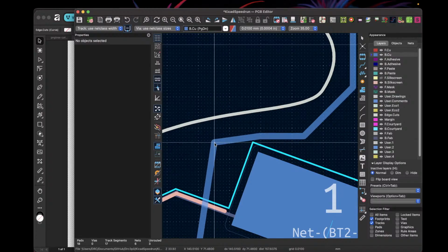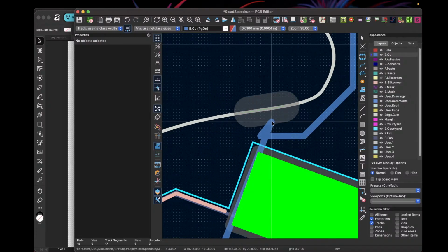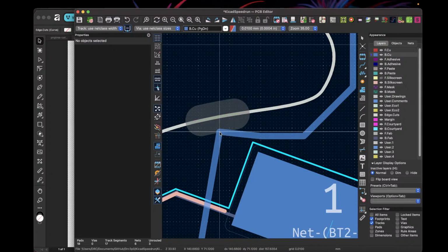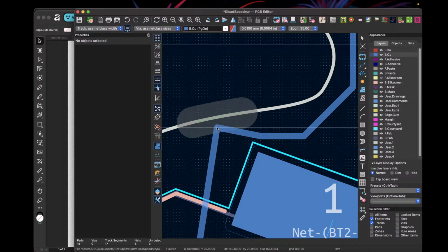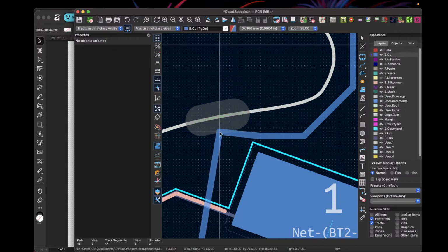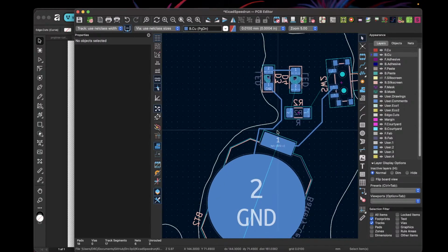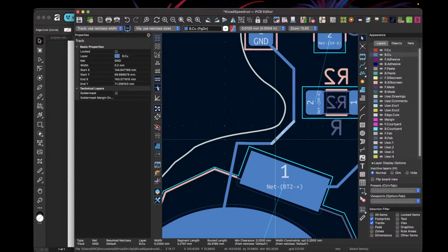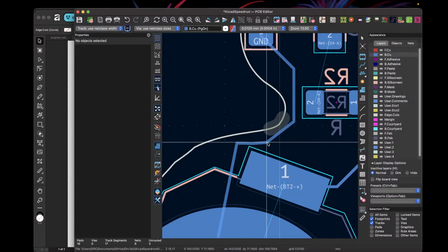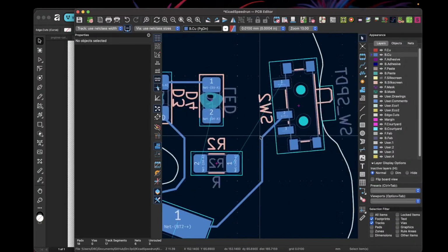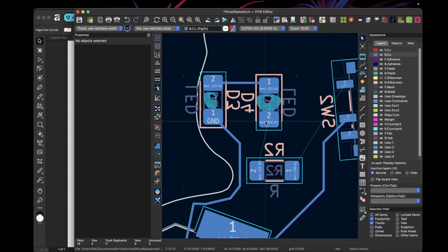You can kind of adjust stuff, and you see, it lets you know you can't get too close to the edge cuts. You can change those preferences so you can break the rules a little bit more, but I recommend not to. There's reasons that they have those tolerances built in. I think even the way that I have my traces set up is kind of my own custom thing, that I'm able to do the free angle bending for it. But it's not too different from how anybody else would experience.